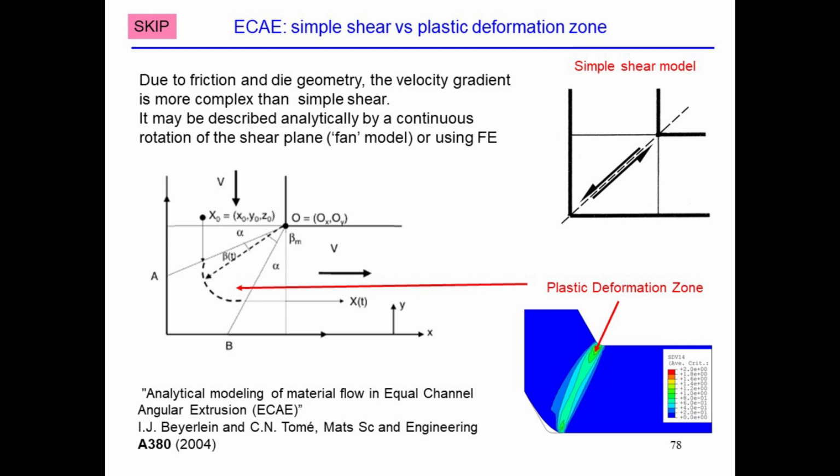So you apply your shear gradually into your material. You can easily implement that using what we saw yesterday: if you have a non-homogeneous deformation history, that analytical expression was programmed and put into VPSC as a history of deformation, and that is what was imposed to the code. But today we are doing just simple shear.